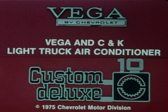The orifice tube with cycling clutch air conditioning system, referred to in this program as the OTCC system, is used on current models of the Vega and on C and K series light trucks. The OTCC system offers simple design and improved fuel economy, since the refrigerant compressor does not operate continuously. For this reason, there will be wider application of this system in future model years.